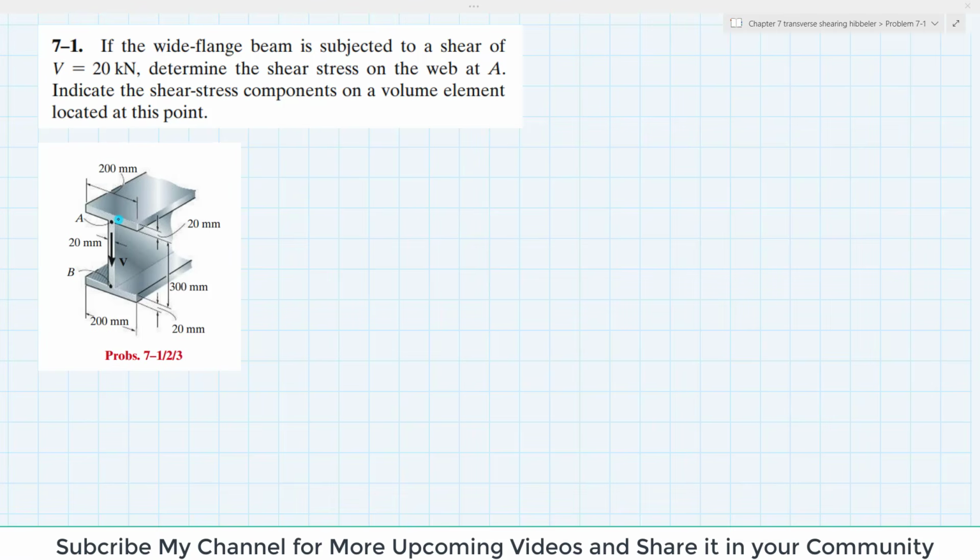So you can see this is a wide flange beam. The shear force V is given as 20 kN. All the values of the cross-sectional area of the wide flange beam are given. This is the width of the flange. This is the total height. This is the thickness of the web, and you have been asked to find the shearing stress component at point A and also determine the shearing stress at this point A. So let's start with the solution.